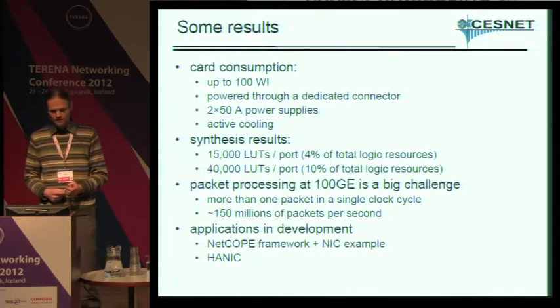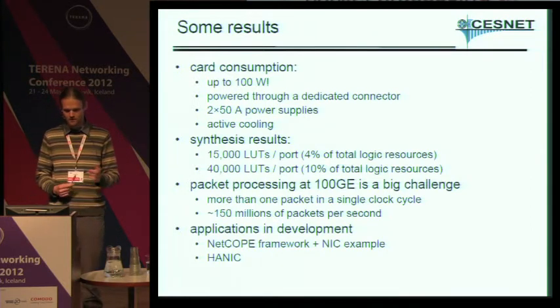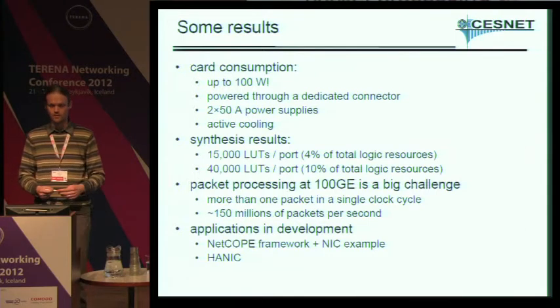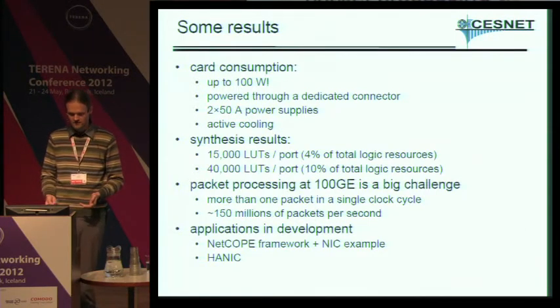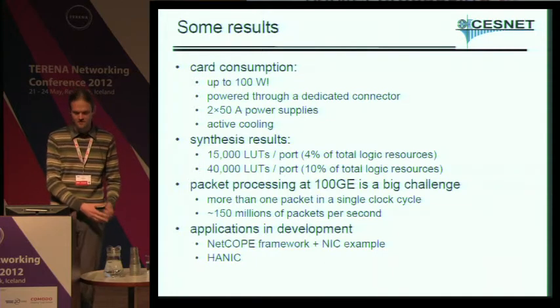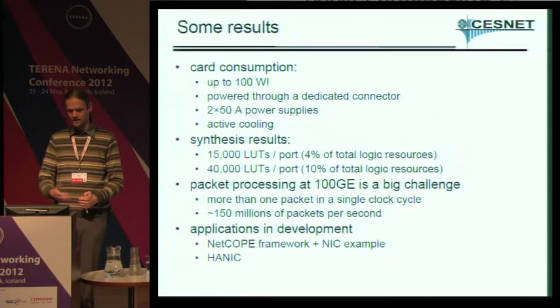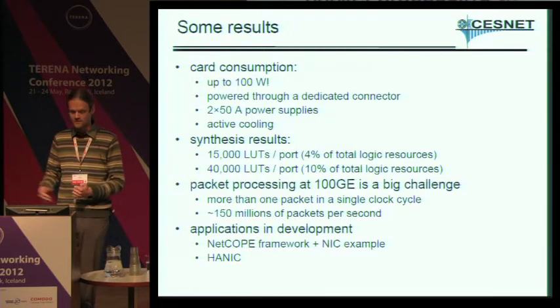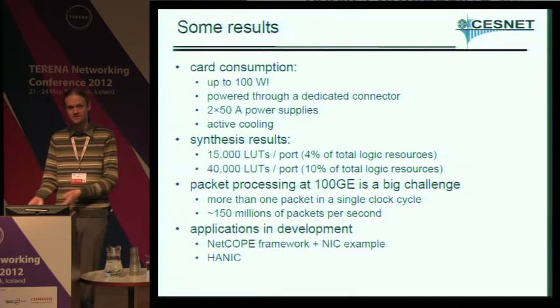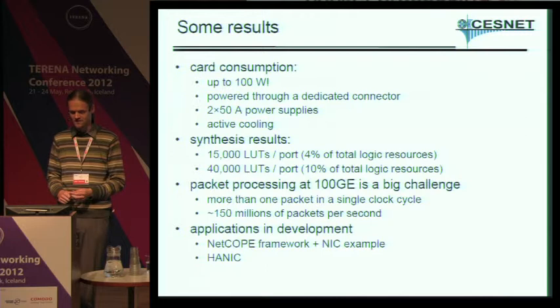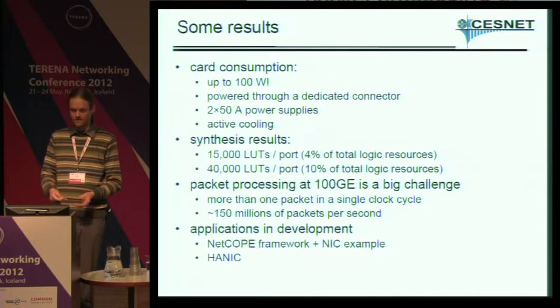We are already preparing applications for this card. The Netcope is our framework for the development of other applications. Netcope takes care of the PCI Express communication because it's always the same. It takes care of the Ethernet communication because every application in our card uses Ethernet communication. The network interface card example is really the simplest possible. It does nothing more than just handle the packets, sending them from the Ethernet to the host RAM and from the host RAM to the Ethernet.